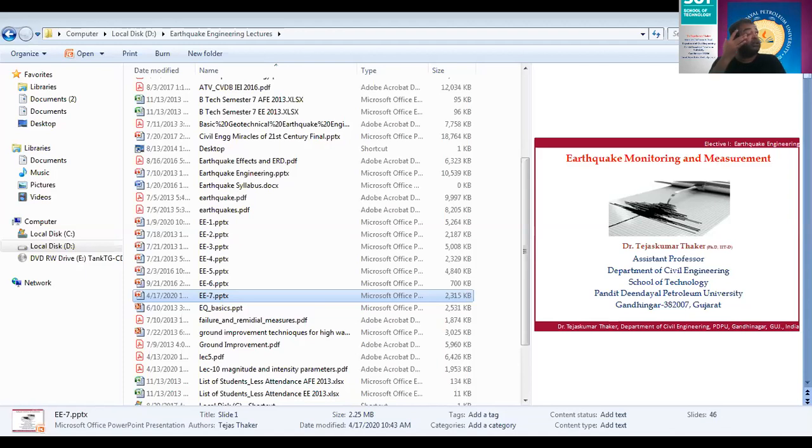In the same way, we have also discussed what the magnitude is. We have defined there are 4 types of magnitude scale. ML, which is known as local magnitude, was given by Richter. Then MS, which is the surface wave magnitude, the body wave magnitude, and lastly, the seismic moment magnitude. We started last time with ML magnitude, which is the Richter scale magnitude or local magnitude. We defined how this local magnitude can be calculated with the help of seismograph recordings, and how to read those recordings to find the value of ML.